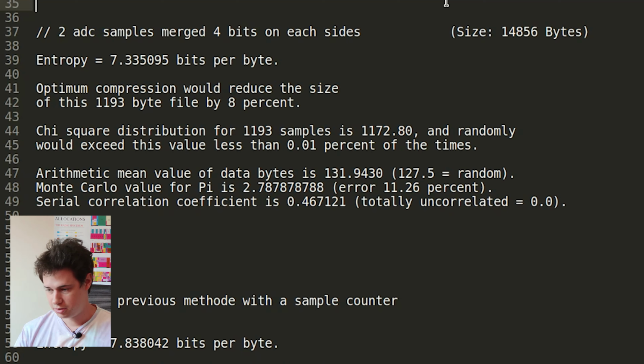Then we get the arithmetic mean value that is at 131 in that case. A lot better than before, still not perfect, but a lot better. The issue before that was we had only very small values, between around 30, 40, 0x14 hexadecimal, which is okay, nice, but not enough to fill out the FF range. So there, by combining two of them, we get a higher spectrum, and of course the average goes up and is kind of close to what we would hope for.